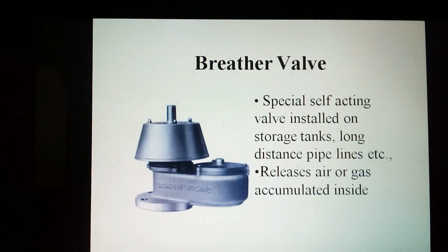The range includes pressure only, vacuum only, and combined pressure and vacuum valves, all available with flange outlets or vented to atmosphere. Pressure and vacuum release valves are used extensively on bulk storage tanks, including fixed roof tanks with floating covers, to minimize evaporation loss.